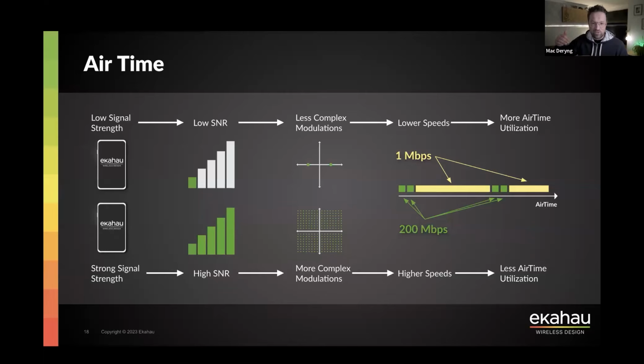And now when you compare that to a high SNR transmission, where you have high RSSI, low noise, then you can use more complex modulations. And now maybe instead of sending at a slot time 1 or 0, or maybe 2 bits if you're lucky, you will now be sending 10 bits, or in the future, 12 bits at a given time, okay? You might be talking so much faster just because you have higher SNR. And this talking slower, talking faster, we call that the MCS rates, you know, it will affect the data rates. It's subject to a more detailed discussion.